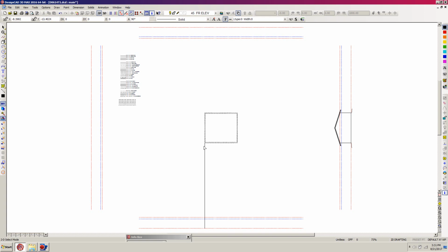And now I'm going to trim this line on down. Now if I try to trim it to this ceiling line right now, what it's going to do is pull this bottom portion of the line up instead of bringing the top down. So before I trim that, I'm going to select it, and I'm going to use the extend command, which is essentially the dash command, and so shift dash, or actually it's underline, and click near it, the top where I want to hit it. Just click and hold the button down and get down to about a little bit above the ceiling line and let go. And now I can trim to the ceiling line by hitting E and just trim to it.